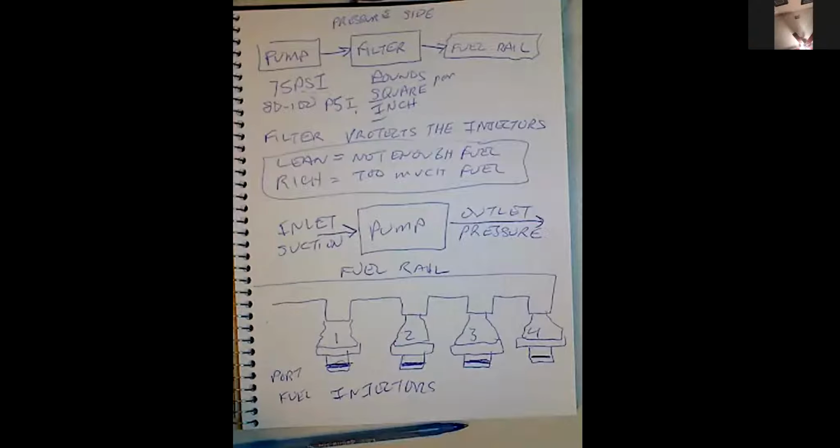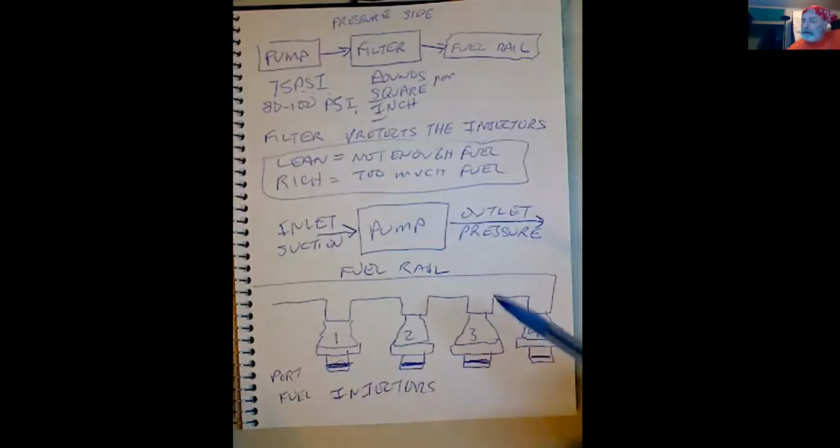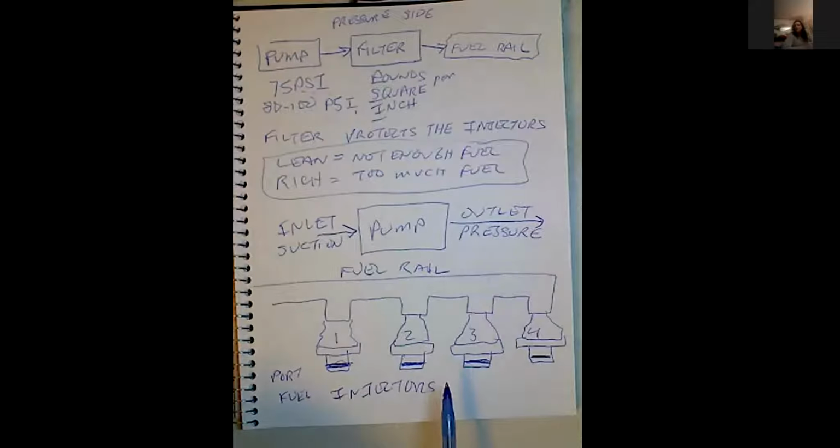The whole purpose of the compression stroke is to increase the pressure, because that increases the temperature, and that's going to vaporize all that fuel and make it much more explosive. It's going to give us better performance and better emissions as well. It changes the phase, yeah.